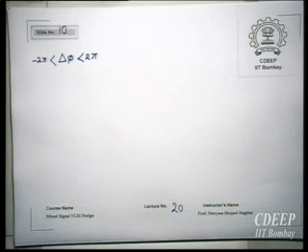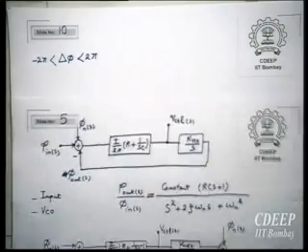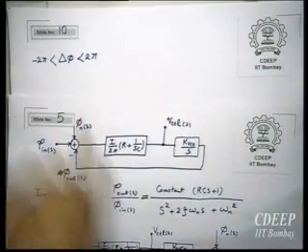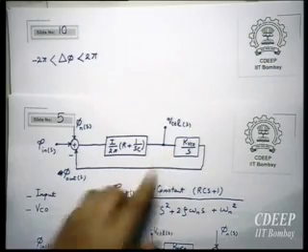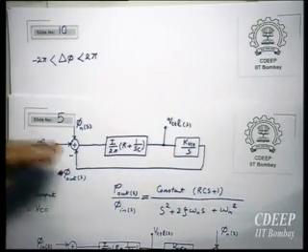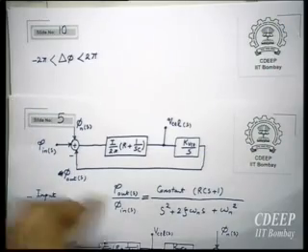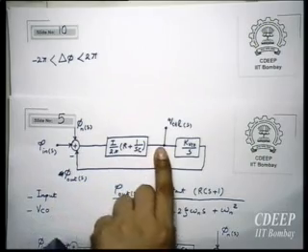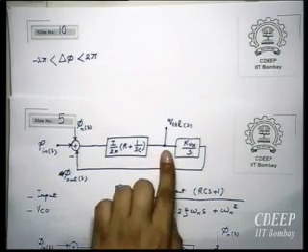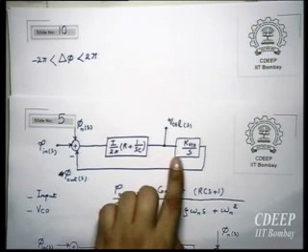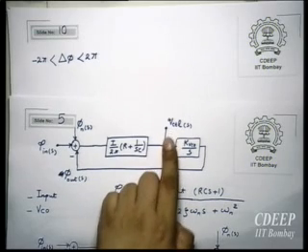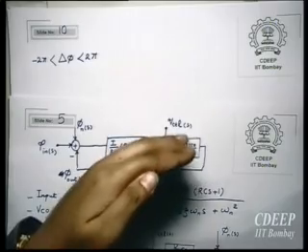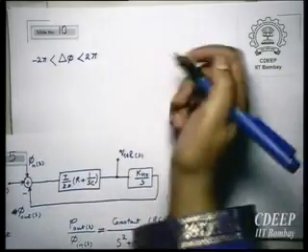But after all, whatever I get, if I apply a delta phi in this range, when it settles in response to this delta phi, it cannot go indefinitely to a large value, as we discussed, because anyway there will be a limitation. For example, the VCO cannot respond to voltage values above some value. The VCO also has its own range.